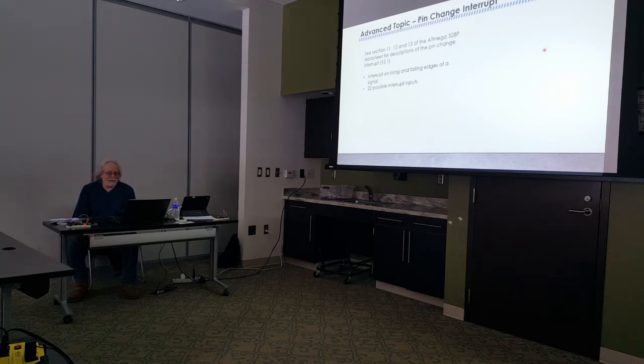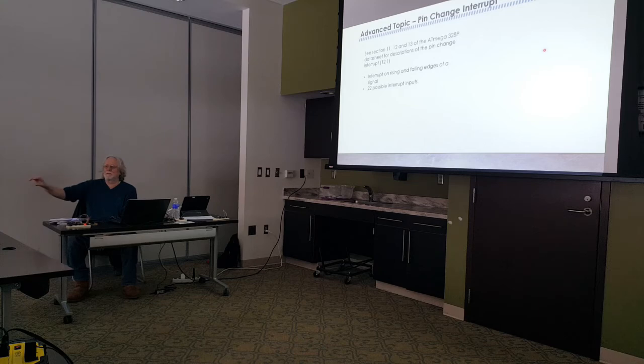It does require a little bit of manipulation of the data you're getting back, because you're going to read a port register. You're not going to use digital read and digital write. You're going to say keyboard is equal to port A. So when you read port A, you're going to get 8 bits, and now you have to figure out what to do with 8 bits, not just 1 bit.